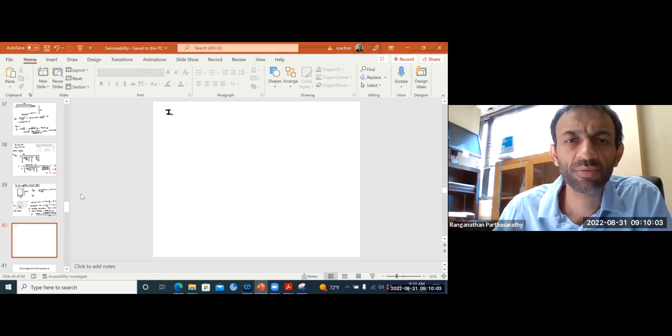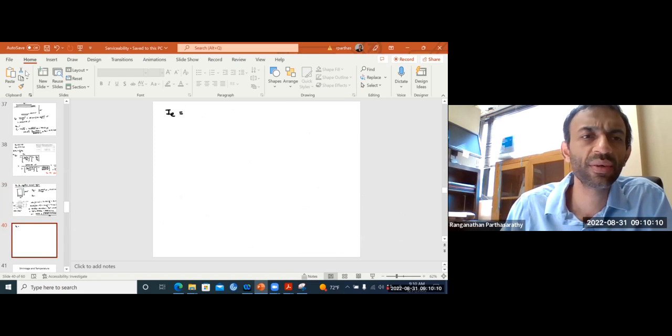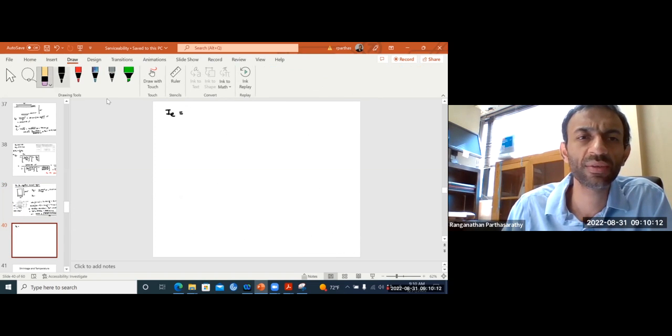So what's your effective moment of inertia for this negative moment region? First we need the cracking moment.